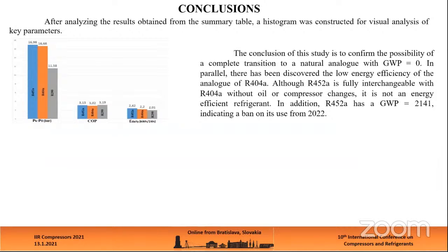Although R452A is fully interchangeable with R404A without oil or compressor changes, it is not an energy-efficient refrigerant. In addition, R452A has a GWP equals 2141, indicating a ban on its use from 2022.